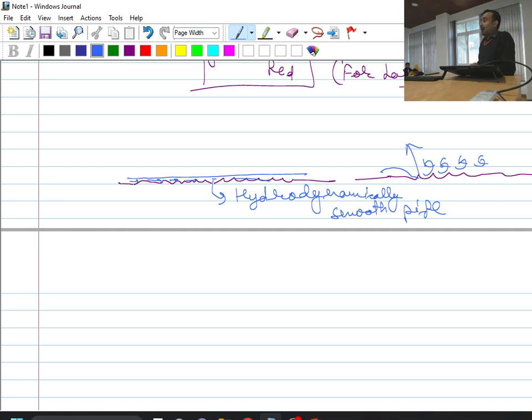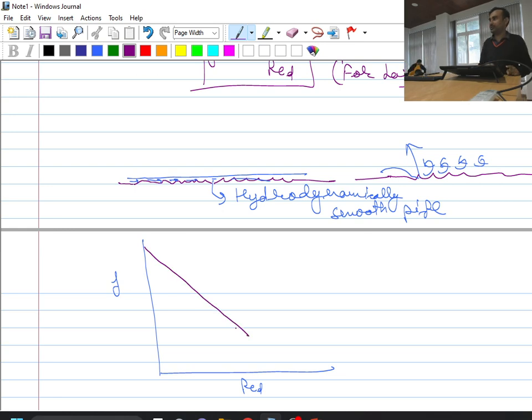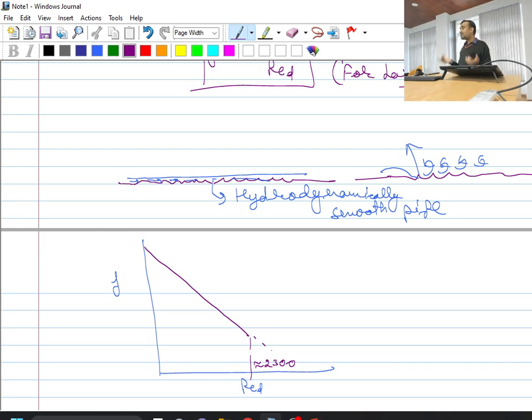Now we have done this discussion, and we came to know that if I plot the Darcy friction factor as a function of Reynolds number, because it is in inverse relation with the Reynolds number, it will be decreasing linearly with the Reynolds number. But this relation will only be applicable for a circular smooth pipe till my Reynolds number is nearly equal to 2300. I cannot extend it after this, because after this the effect of roughness will also come into picture, and also, to estimate the value of f, I have to determine what type of dependence on Reynolds number comes for the turbulent flow.